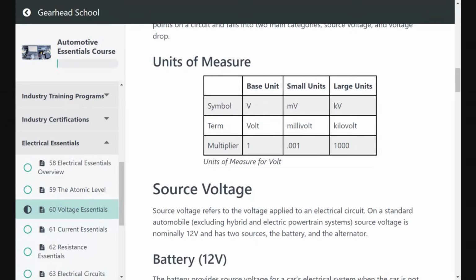15, 20,000 volts was the ignition system. Now we're approaching 40 and 50,000. I mean, some big numbers, because we run leaner and leaner, and the leaner mixture is harder to fire, and then we have higher combustion pressures and turbocharged and the wider gaps on the spark plugs. So you get to some really high numbers on voltage. So kilovolts is pretty much the ignition system.